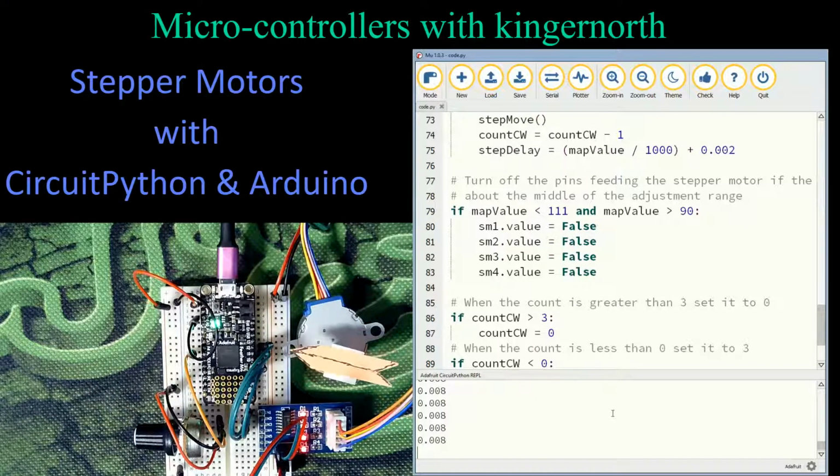So as our time is up, we've gone through an hour now. We can see what happens in here. It doesn't matter whether we're using CircuitPython or whether we're using Arduino. We can make our motor controlled. We can actually delay it. We can get very tight, very good precision on it. Think about it. We have 512 indicators in there, and we have a gear ratio of 16. So we actually have very, very fine resolution on this motor. There are more detailed motors, the ones that even move finer, but then they have slower overall RPM. So you have to find the trade-off.